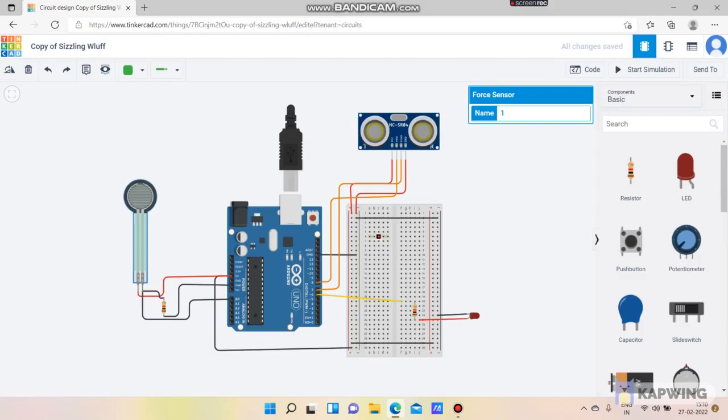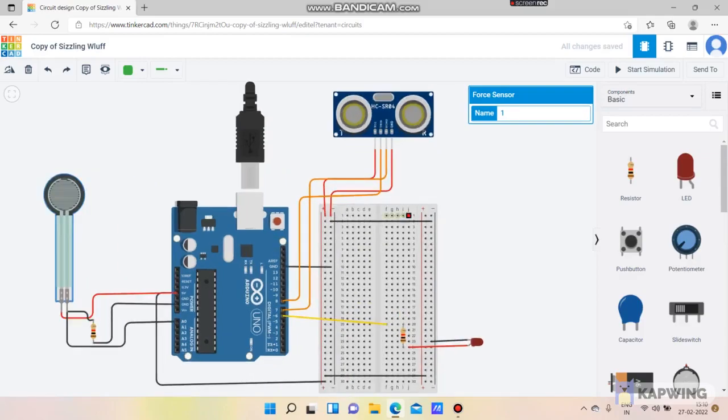So first I will explain the connections of our breadboard. So as you all are able to see, I have maintained this positive pin at 5 volt by connecting the corresponding 5 volt pin of the Arduino Uno, and I have maintained these negative pins as ground pins. Similarly, on the corresponding right hand side pins, this positive I have maintained at 5 volt and negative as ground pins.